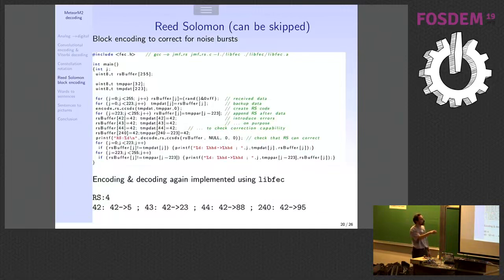And if I run this in my Reed-Solomon decoder, indeed LibFEC detects 4 corrupted bytes, and these 4 corrupted bytes are these values which can be recovered. So not only do you discover which bytes are corrupted, but you can find the proper initial values of these bytes. So, just a demonstration. Again, you have to run it by yourself. I can talk as much as I want. If you don't run it by yourself, you don't learn, so try it by yourself.